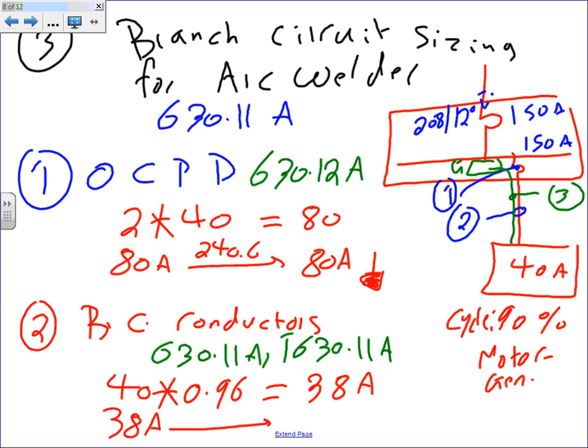I'm going to take it to 310.15(B)(16). Let's assume, guys, it's typical equipment, 60-degree column, unless I know otherwise. What's the conductor under the 60-degree column that can carry this amount? Number 8? Can number 8 carry it? Number 8. Okay.